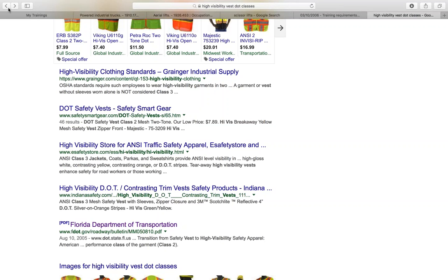Okay, and then guidelines for safe operation of heavy equipment, right? What are we looking at? We want to follow the safety protocols in order to minimize the risk of any injuries, illnesses, or fatalities, right? So what are we looking at? Basic list items, right, that have to be checked daily. Engine performance and gauges, oil pressure and levels, housekeeping tasks, fire extinguishers, making sure all audible warning devices are working, any anti-two-blocking devices are in place and working, and that's on a crane.